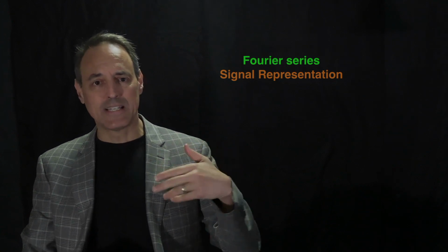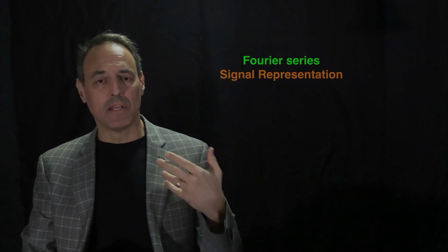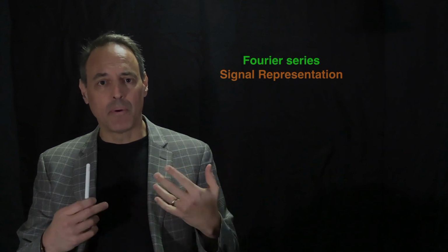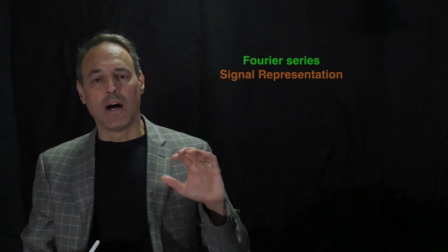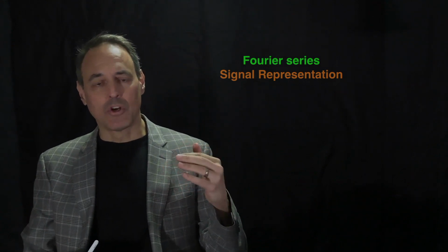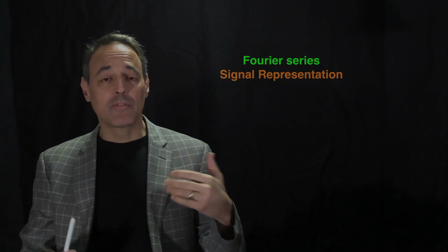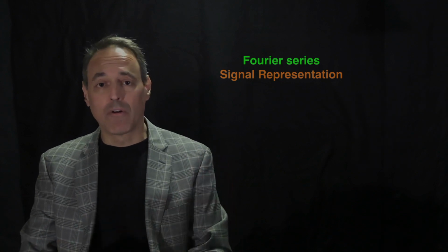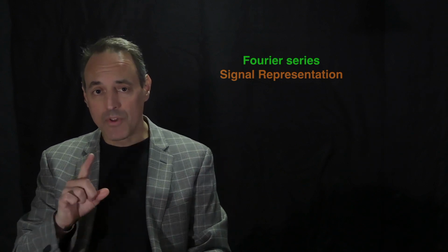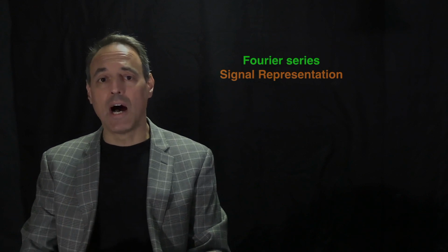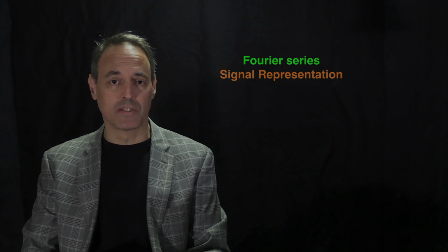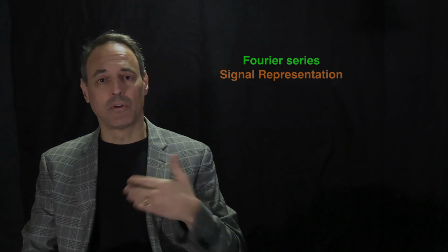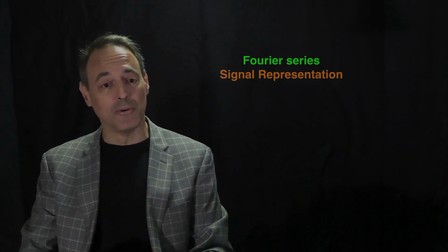These are essentially harmonics of a basic signal, and we're going to build up a representation of any signal in terms of these harmonics of cosines and sines. And we're going to find that it's going to be a really powerful representation. And more than that, we're going to find that these, in fact, are eigenfunctions of LTI systems, which is really what makes them so powerful from just a purely mathematical manipulation point of view.